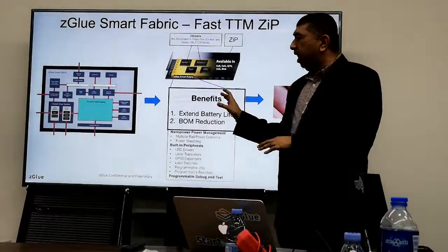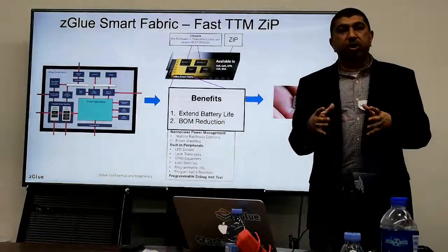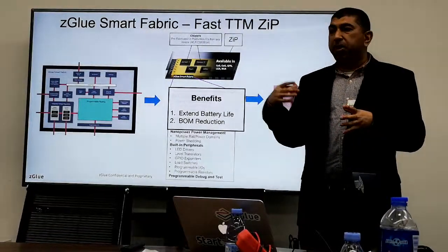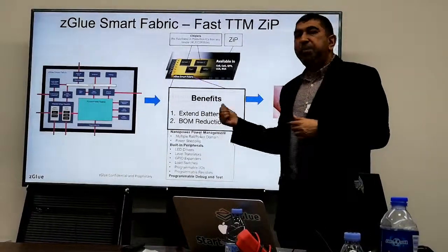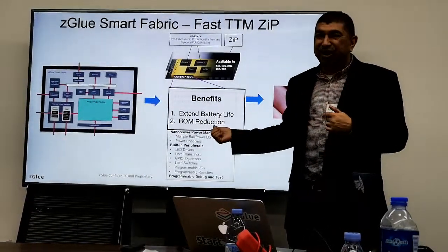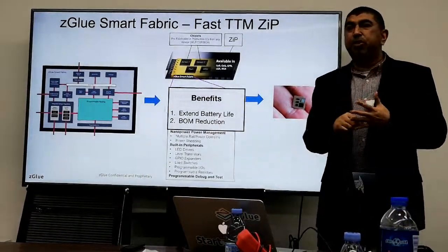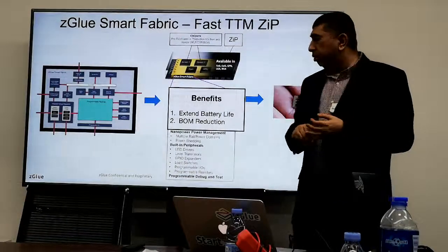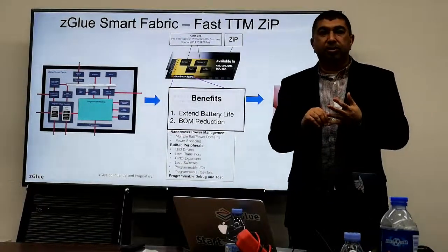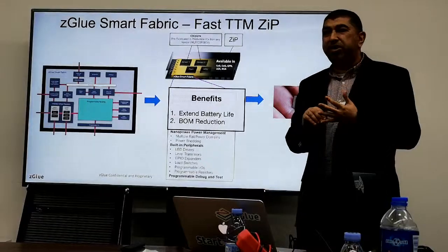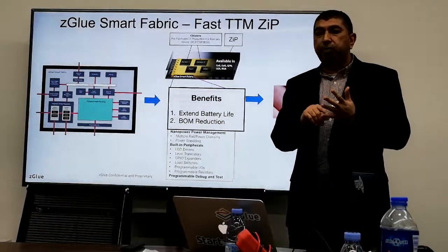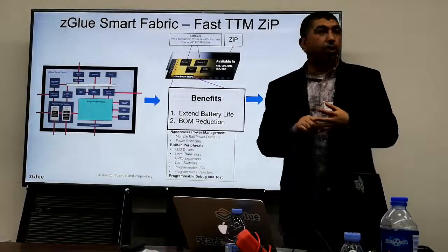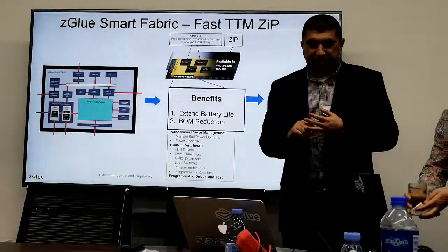If you try to do any of that type of thing on a printed circuit board, you will need to buy additional chips, right? What we did is we embedded all of that in here. So for the first time, if you are a board designer, you can now dynamically change the voltages of different rails. You can do power gating, which in this context is called load shedding.